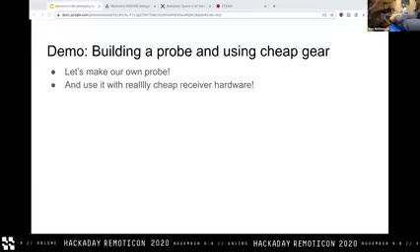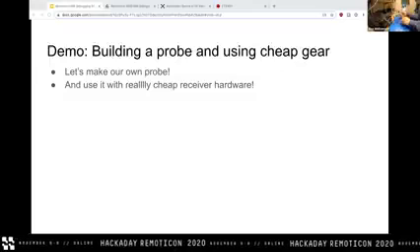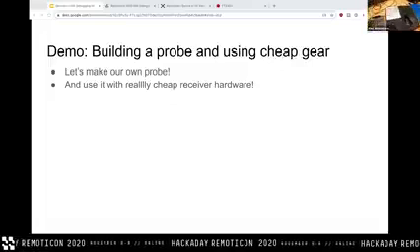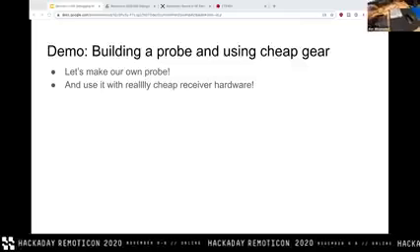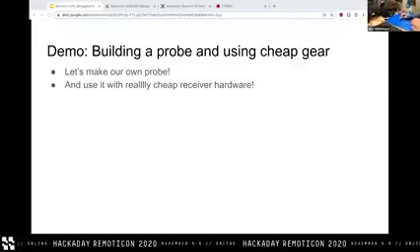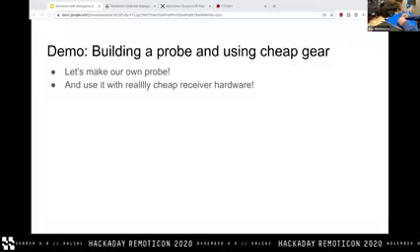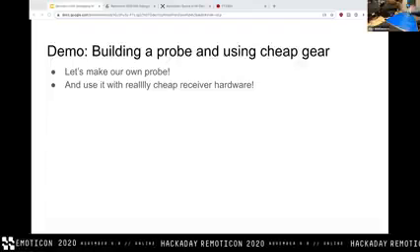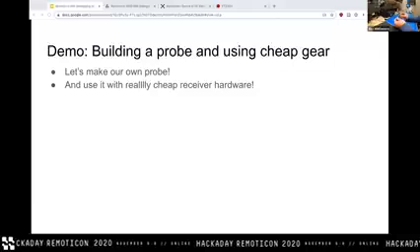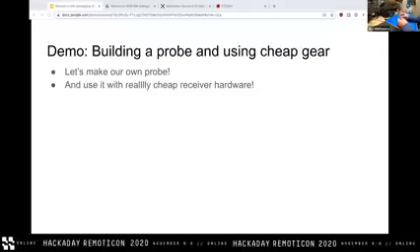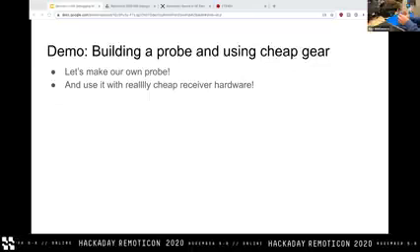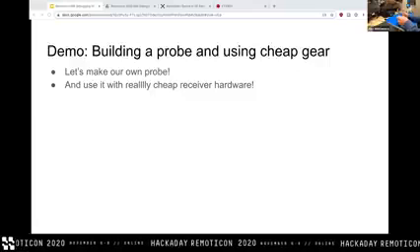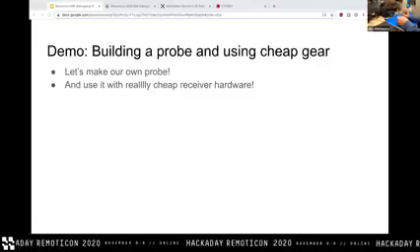pull my LNA off here. This is a critical aspect that I didn't cover. I covered this in the instructions, but the way we'll be powering this particular LNA is via a bias T. So I didn't want to offer a shopping list with a bunch of USB power supplies, even though I'm sure everyone already has one anyway. I wanted something that was easy. Basically, a bias T works by setting a DC voltage on the input to the SDR, and then this device is powered by that offset voltage on its output side.